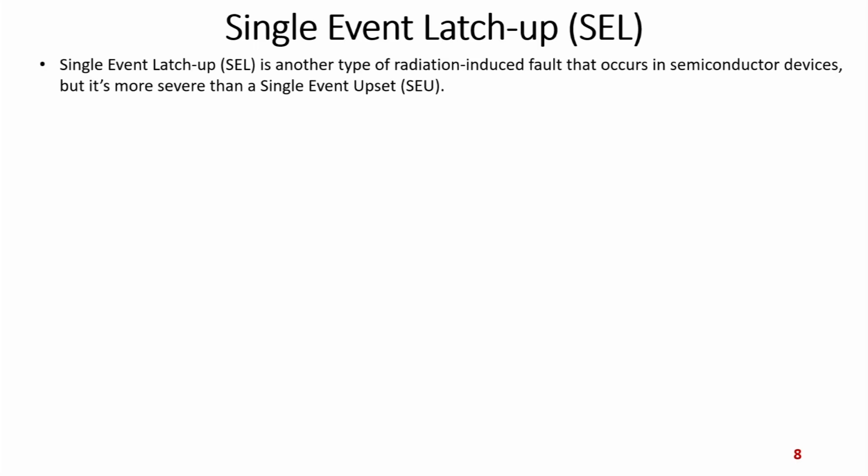The next phenomenon is called single event latch-up. Now we will try to understand what latch-up is. It is something like a short circuit, and it is not a temporary one but a permanent one. Single event latch-up, or SEL, is another type of radiation induced fault that occurs in semiconductor devices, but its severity is more than the single event upset.